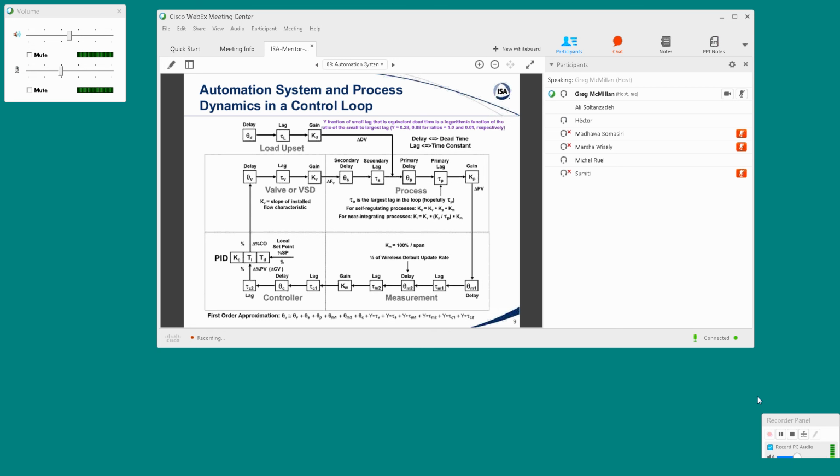Let me say this, some tuning methods focus on that. The secondary lag comes often from heat transfer and sometimes from mixing, but principally from heat transfer lags, heat transfer surfaces. Lambda tuning focuses on that. I've been shown test cases where the secondary lag was quite large compared to the dead time, and they show how much better lambda tuning is than other tuning methods. Well, if you made a first-order approximation and took that secondary lag as dead time, you would have increased your rate time, and you wouldn't see the big benefit.